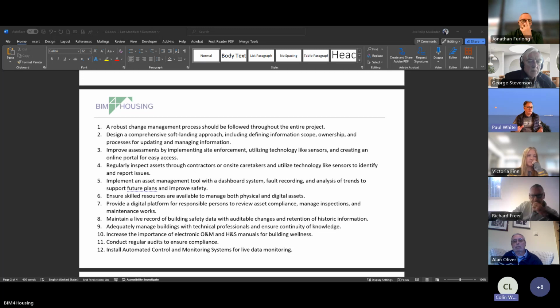But certainly from a fire and smoke safety point of view, you keep ignoring these things, which is what everybody's been doing. I was worried when somebody said they'd just been on a level 4 risk assessment course, and they didn't mention smoke control and ventilation fire dampers. And I'm thinking, well, what's the point? These are the things there to protect you in a fire. They're hidden, but if they don't work, you're in trouble. And yet they're not in a risk assessment requirement.